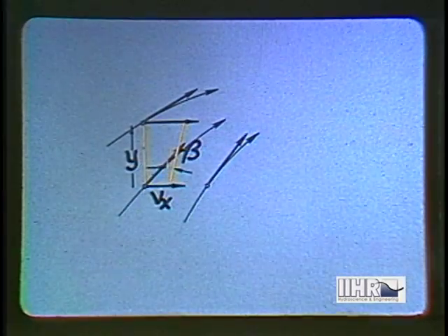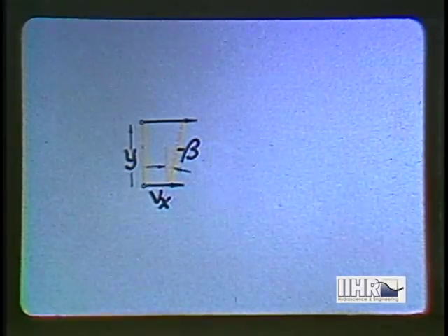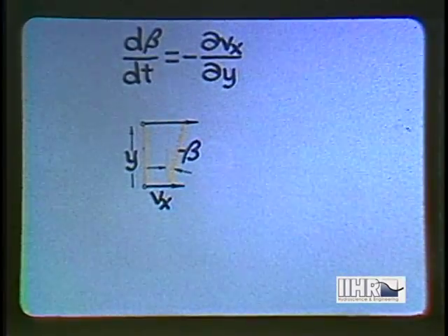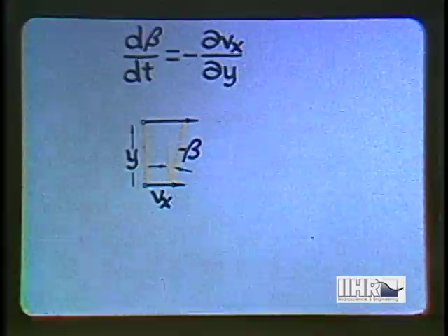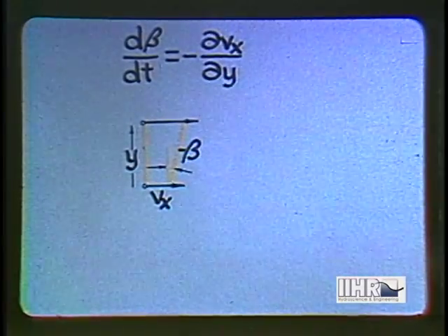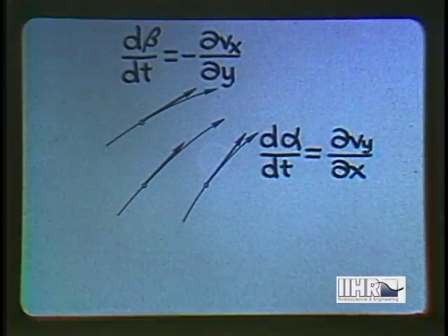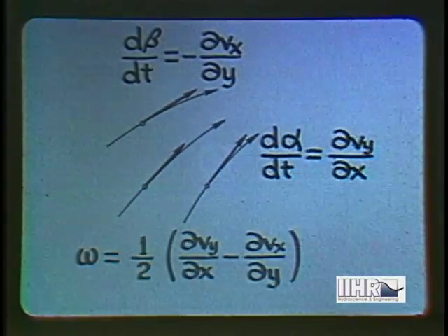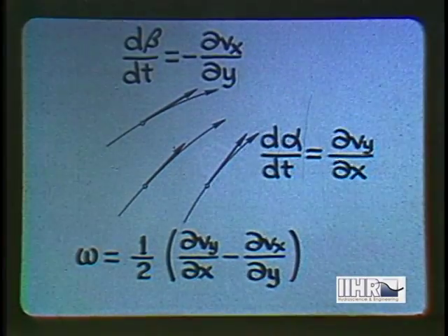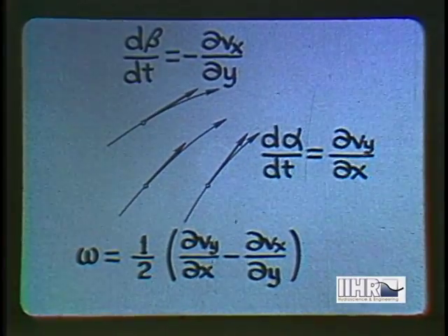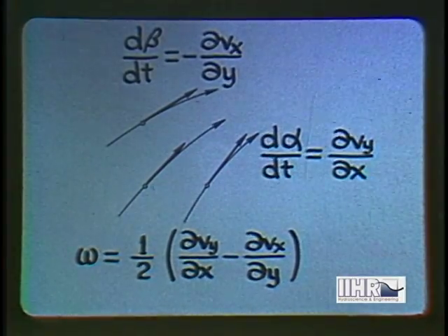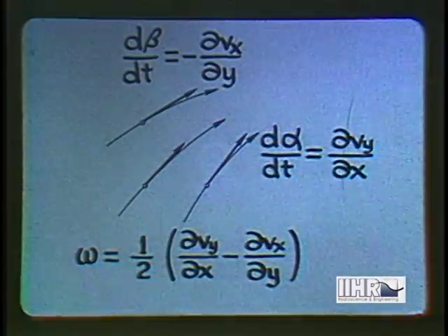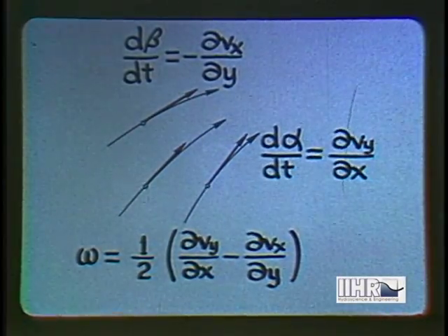The same is true of a line or stick in a direction that is perpendicular to the first, a negative velocity gradient now indicating rotation in the same positive sense. The net vorticity in a given plane depends upon the average of the velocity gradients in the two normal directions. This in turn would be indicated by the average tendency of two lines or sticks at right angles to each other to rotate. In the case of water in a tank rotating about its axis, the velocity varies directly with